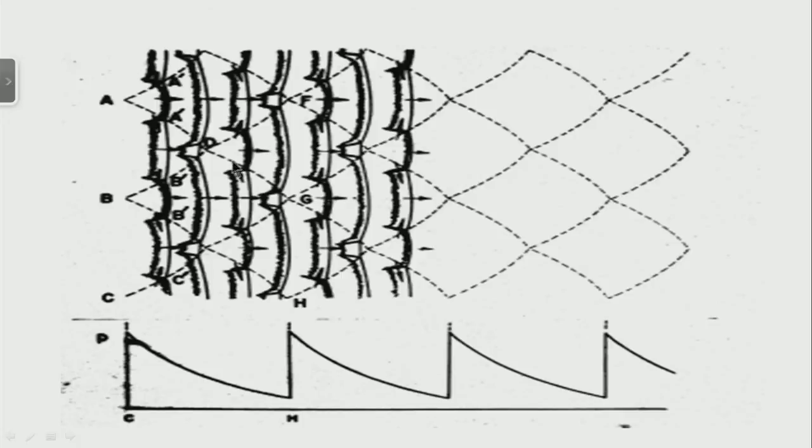Therefore, in the adjacent cell, over here I have incident waves, that means I have the triple point intersecting here, again a Mach stem shock being formed gets into the incident shock wave. Therefore, the front of a detonation consists of a Mach stem shock, an incident shock in the neighboring cell; in the neighborhood of the other one it is the Mach stem shock followed by incident shock, and this is the front of the detonation.